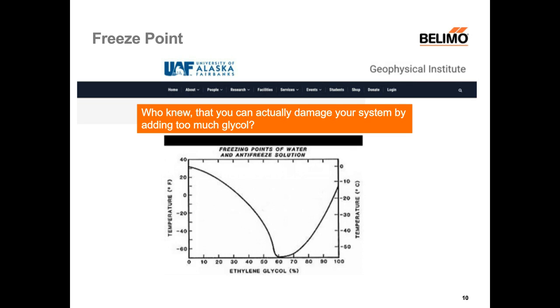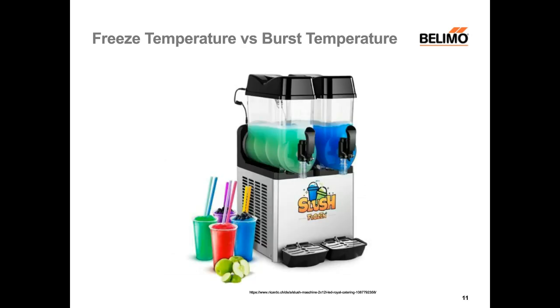Okay, now when glycol water mixtures are cooled down, then first the water will start to freeze, creating a slurry. That is not good for the heat transfer, so your pump doesn't really like it, but the pipes will not burst if you have an expansion tank. So please check if your application really requires freeze protection or if maybe burst protection is enough, because in that case you could use a lower glycol concentration, and that's actually 5 to 10% difference.